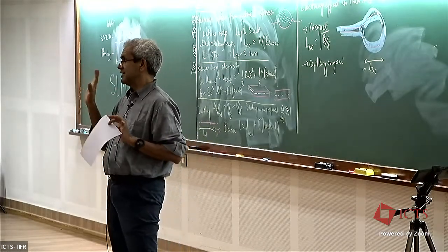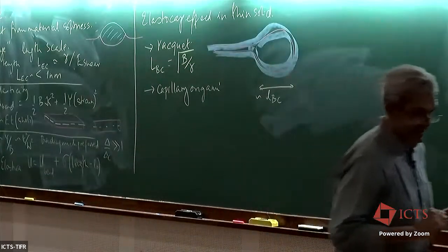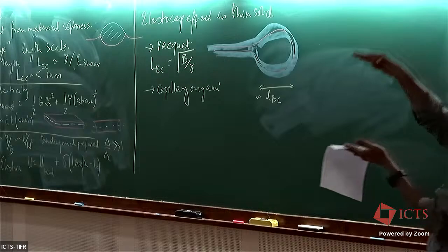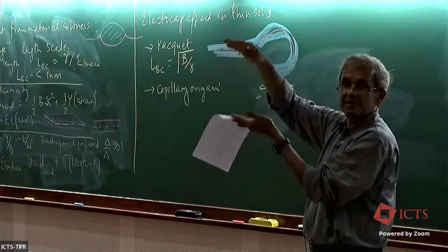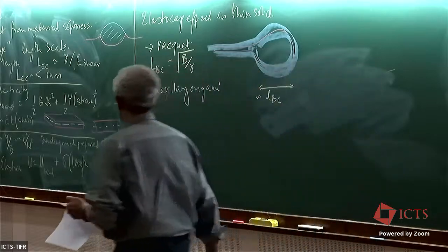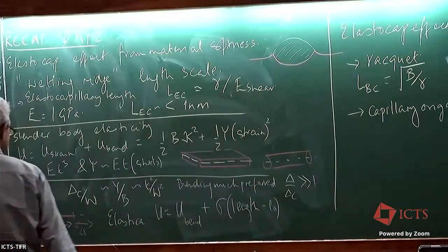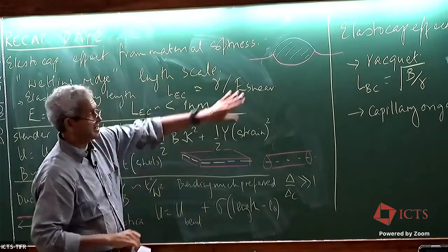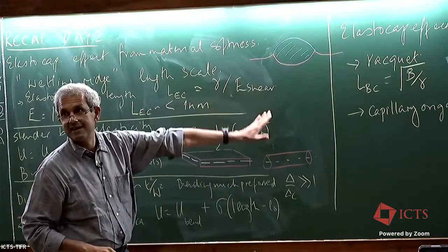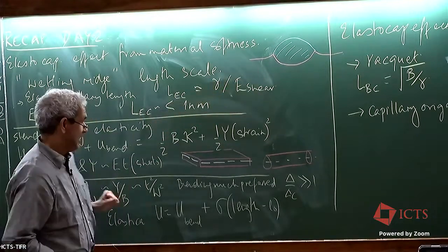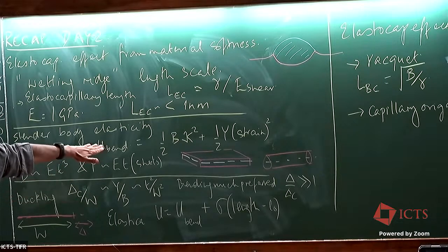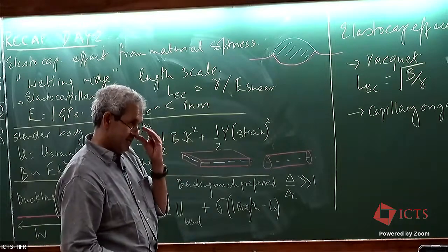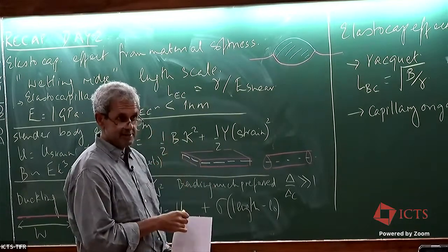So then we invested, I don't know, 20 minutes talking about how you start thinking about the elasticity of thin objects, how you abstract from E bulk and E shear, or from Young's modulus and Poisson ratio, to slender bodies. The idea was, we really don't want to care about what happens in the thickness of the object, unlike here, where we do care. We would like to abstract some imaginary plane in this object, and endow that plane with rigidity against bending and rigidity against stretching.